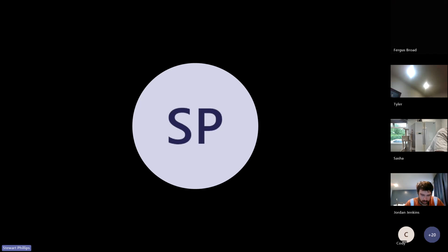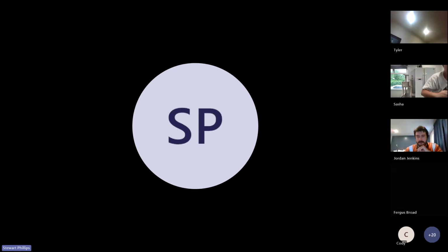Where might we want to use, other than the high rupturing capacity ones, where might a fuse be advantageous versus a circuit breaker? One instance I can think of is a situation where you don't want the user to be able to reset the circuit breaker. If a fuse blows in, say, a motor control, then the user can't just say, oh, it tripped again, reset it. The fuse will break, and someone has to physically come out and have a look. So sometimes a one-time use is a good thing. That means someone can't just flick it back on.